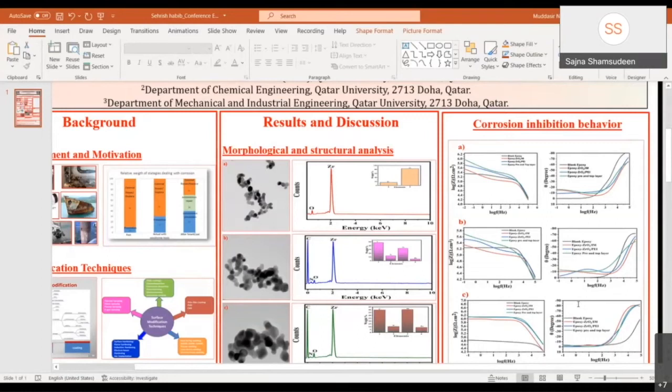The results show that with the passage of time, the blank epoxy coating starts to deteriorate because there were no chemical species inside these coatings which can protect them from corrosion propagation, and also due to the formation of conductive paths in the coatings, water starts to move into the coatings and corrosion starts to propagate.